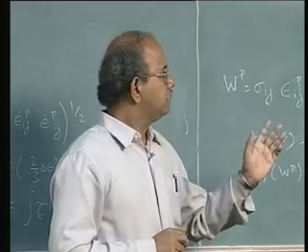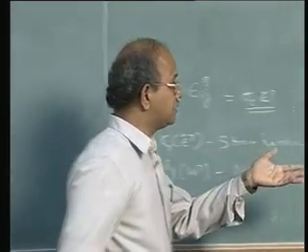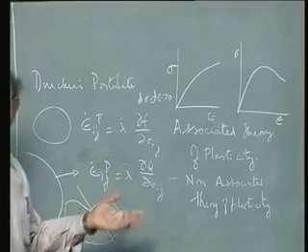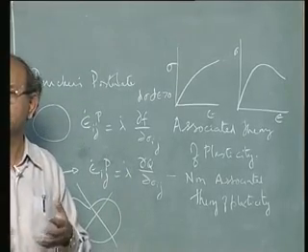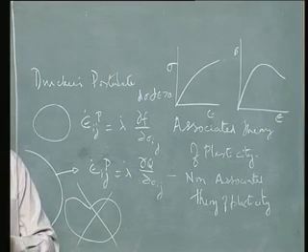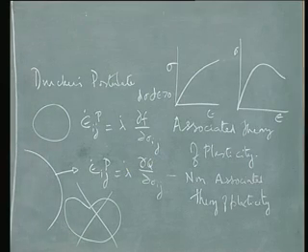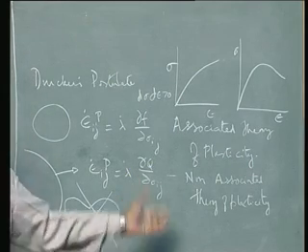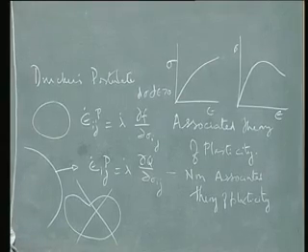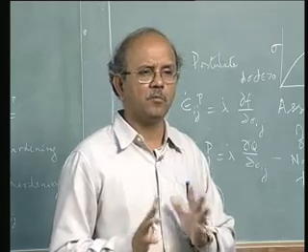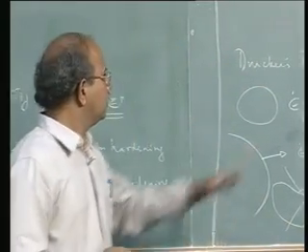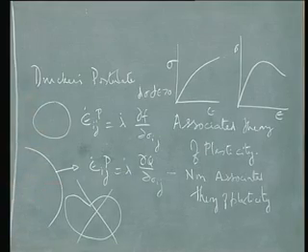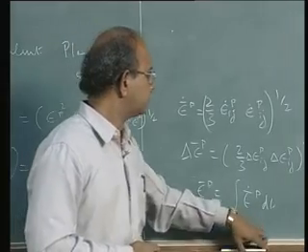So in other words, the techniques for soils have to be changed a bit. Not that we are far away from it, we have to change a bit. In a programming language, it is just a cut and paste, replace a few of the equations that we are going to develop for non-associated theory of plasticity. In fact, the theory will almost parallel that of the associated theory of plasticity. So having done all this, let us now look at what is dou f by dou sigma ij.